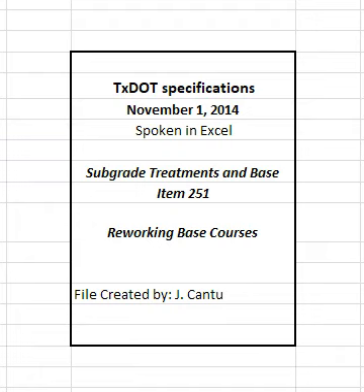5.6 Ton. By the ton of dry weight in the trucks as delivered at the stockpile. The dry weight is determined by deducting the weight of the moisture in the material at the time of weighing from the gross weight of the material. The engineer will determine the moisture content in the material in accordance with TEX 103E from samples taken at the time of truck weighing.